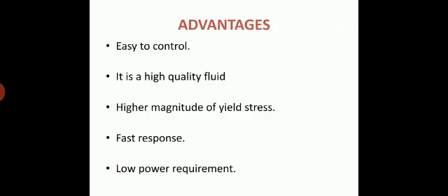Advantages. Easy to control. These magnetorheological fluids are easy to control and it is a high quality fluid and it has a high magnitude of yield stress when compared to the ER fluids, electrorheological fluids, and the response is also faster. And these magnetorheological fluids require less power consumption.